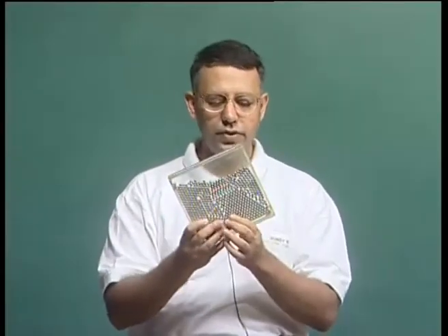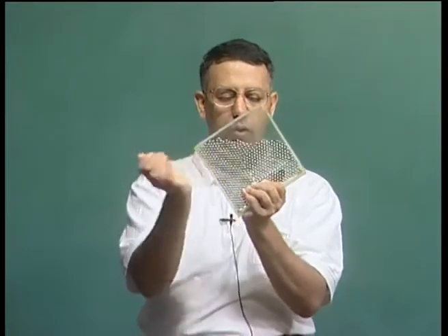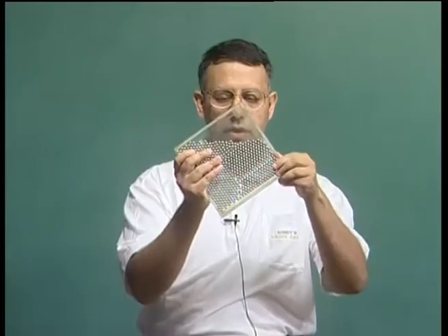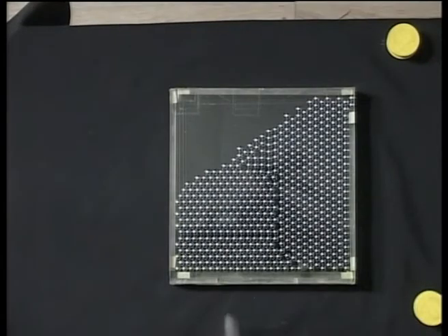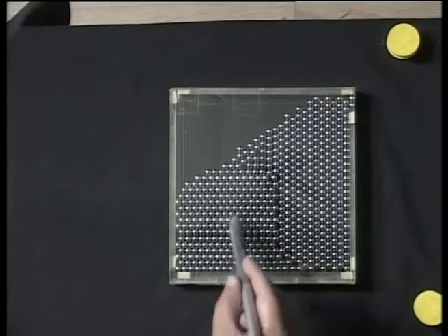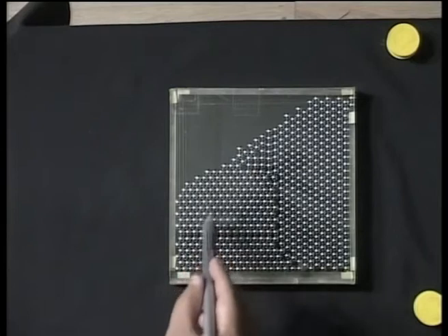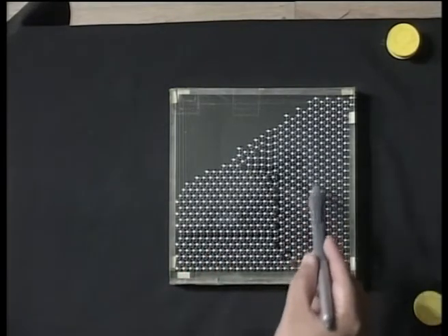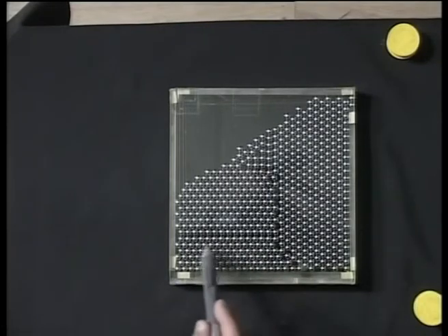So using this toy model, let us see how we can form some of the defects which we have been considering so far. Let me shake this a little bit, and then I have now a structure which I can show you in the other vision, which is the top camera view. You can see here, these balls in this region are arranged in a perfect crystalline array, and this is my high pack density, which is the highest packing in 2 dimensions, the hexagonal packing. Similarly, this region again is arranged in a perfect crystalline array, and this is a third region which is arranged in a perfect crystalline array.